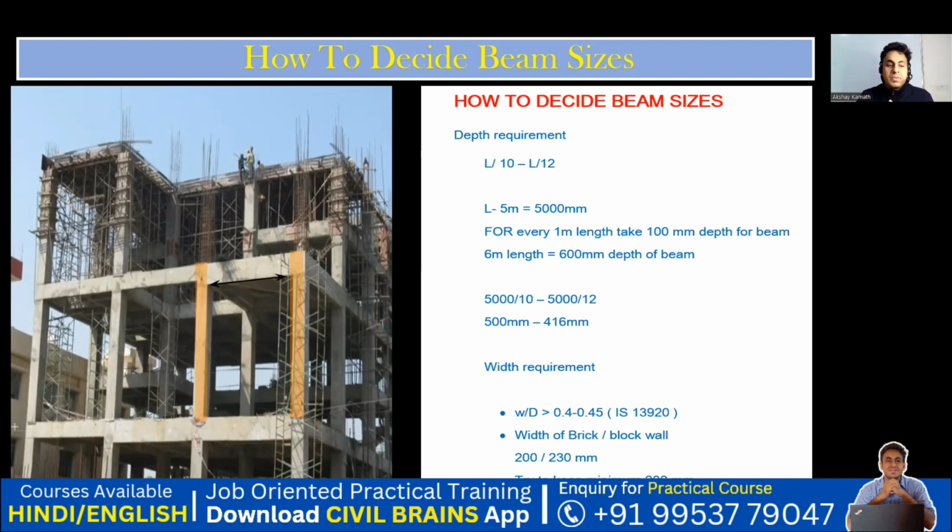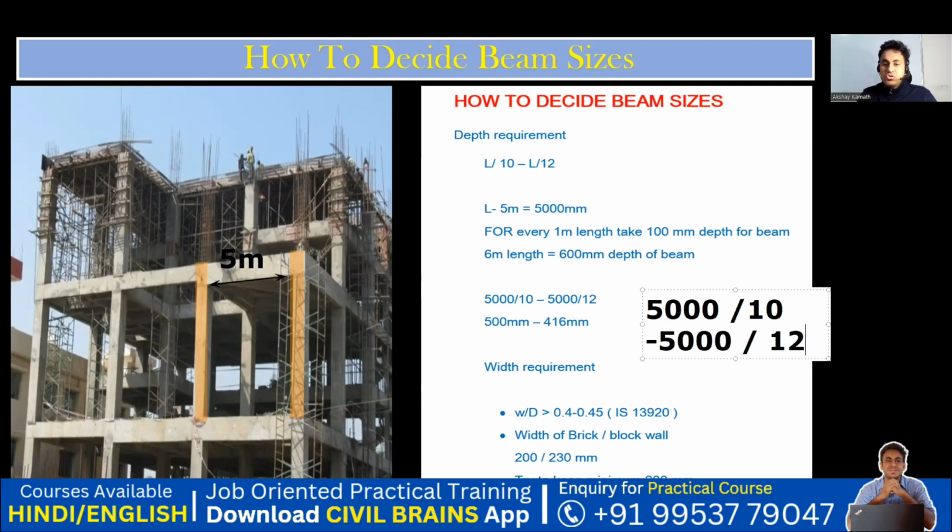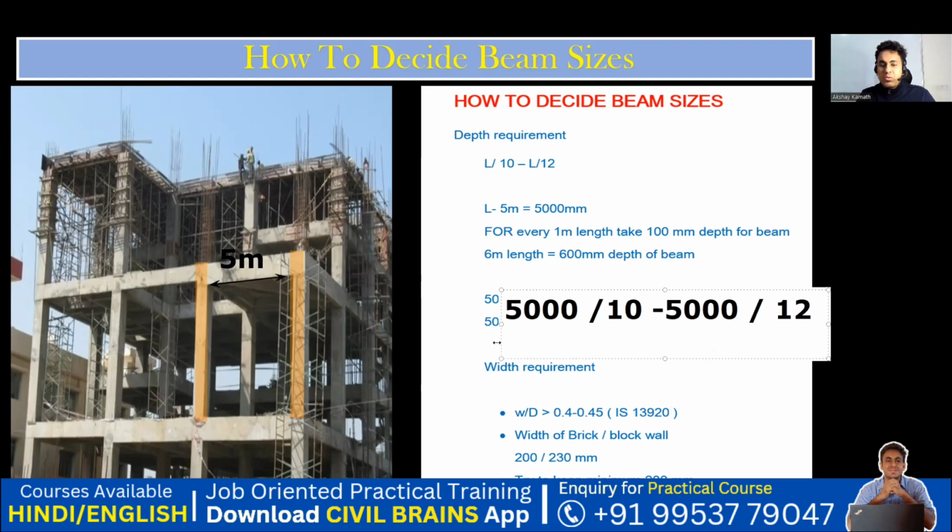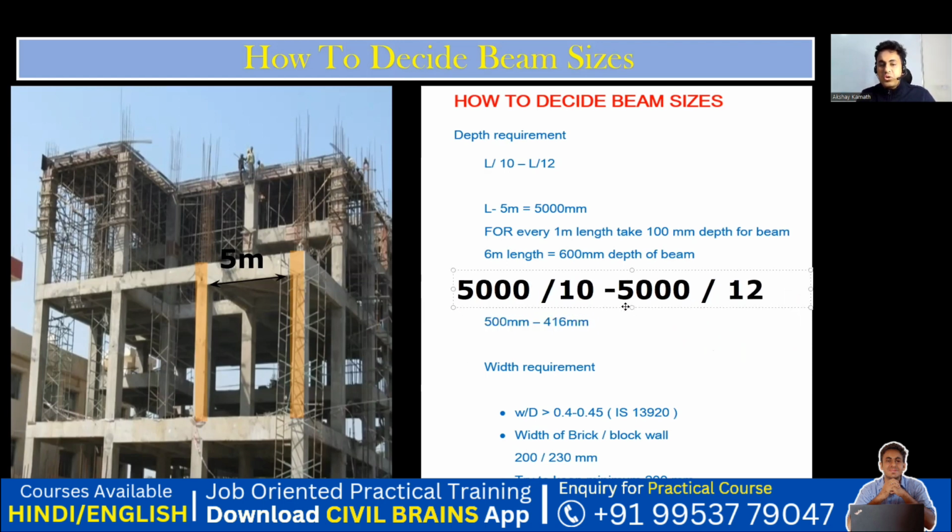Now let us consider this particular span that I have, a 5-meter length. I'll say this is 5 meter. So what is my thumb rule? This should be in mm. So 5 meter in terms of mm comes out to be 5,000. So L by 10 is 5,000 divided by 10. I can go up to L by 12, 5,000 divided by 12. So try to do it manually. If you have a calculator with you, please try to do this.